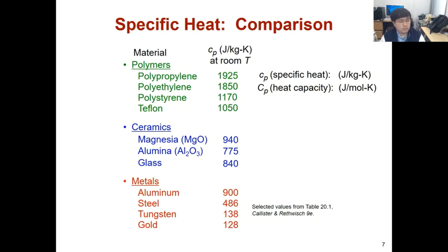But anyway, based on that kind of insight from the atomic structure, polymer, ceramic and metal have different crystalline structures. Metal has a well-ordered crystalline structure, so there is no big movement. However, the ceramic structure will be strongly affected because of the positive and negative ions. If they vibrate, they strongly affect the next atom. That means the vibration is strongly propagated to other atoms. So the heat capacity is slightly higher.